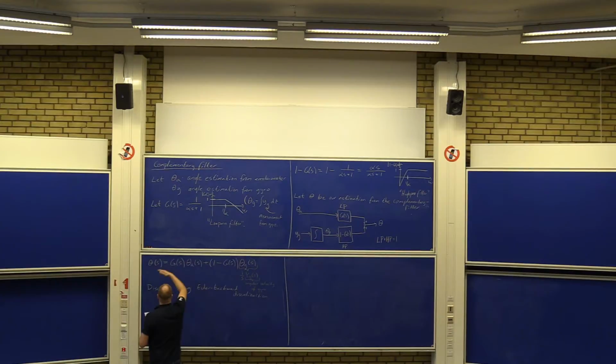If we write this transfer function as the corresponding differential equation, then every derivative in the differential equation we will approximate in this way. So every time derivative will be x of the signal at the current sample minus the value of the signal at one previous sample, divided by h, the sample period.